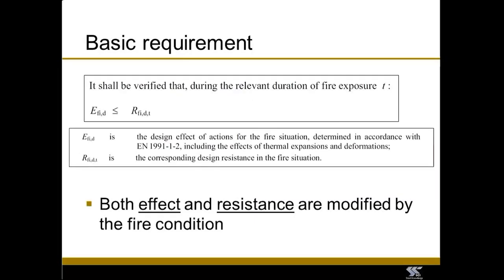So the Eurocode then, what have we seen so far? Well, we've seen that we've got tables of how steel loses its strength as the temperature increases. We've seen that we can plot a standard time temperature curve, which tells us about the increase of temperature with time. Now we've got the basic requirement in the Eurocode, and this is that the